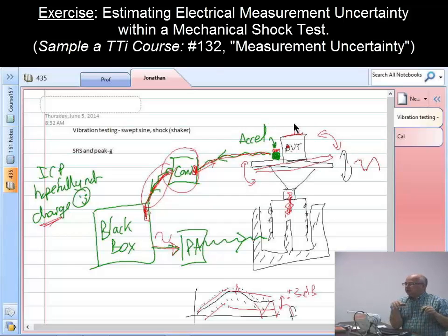And the idea there usually is that we average the accelerometers to try and get the translational components, because if we average, we end up mathematically subtracting out the rotation component. So if you do a multi-point control, how are you still able to do transfer functions?